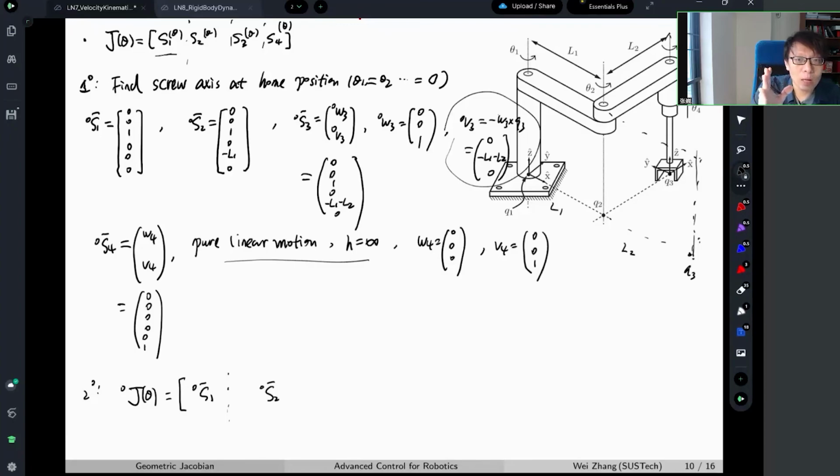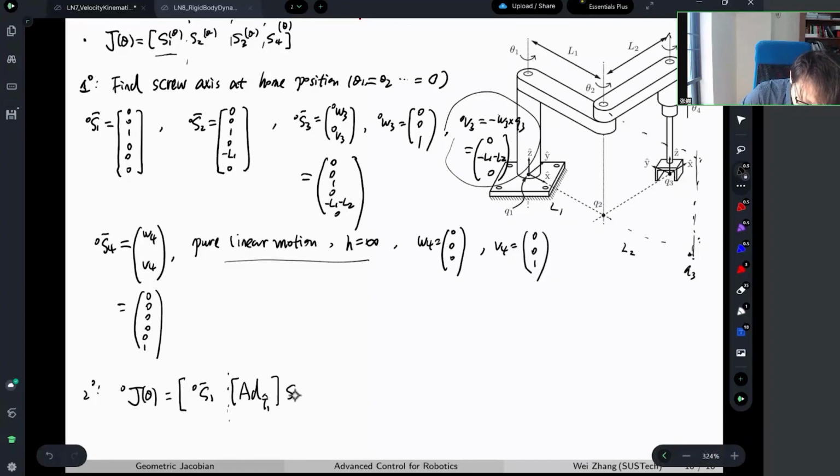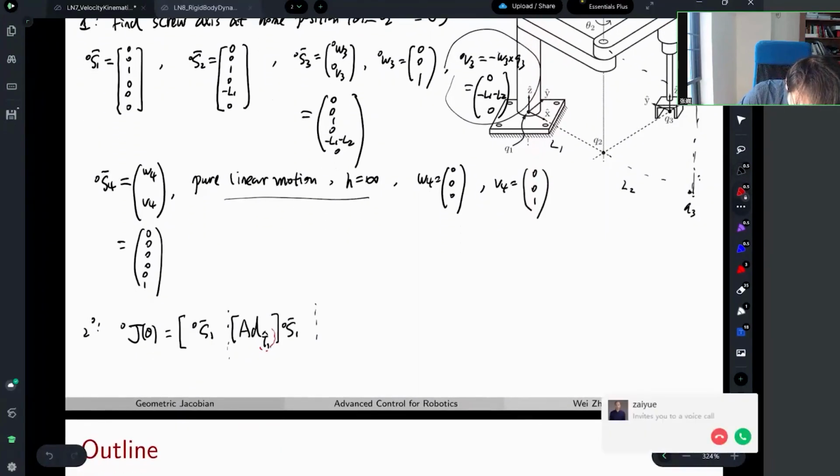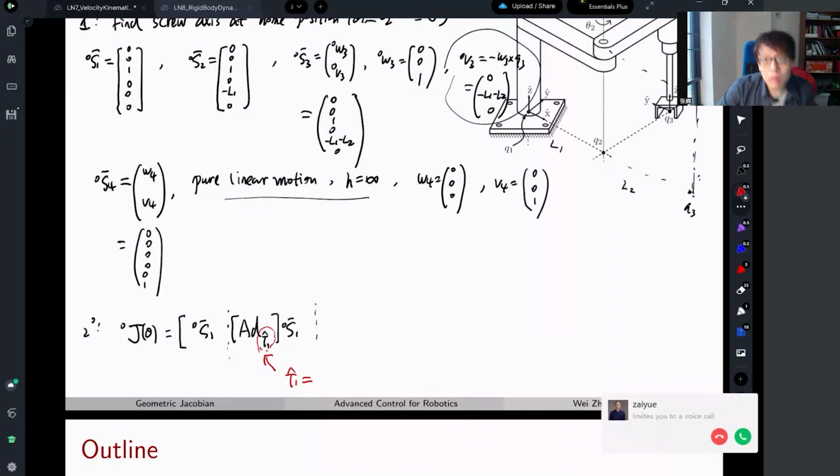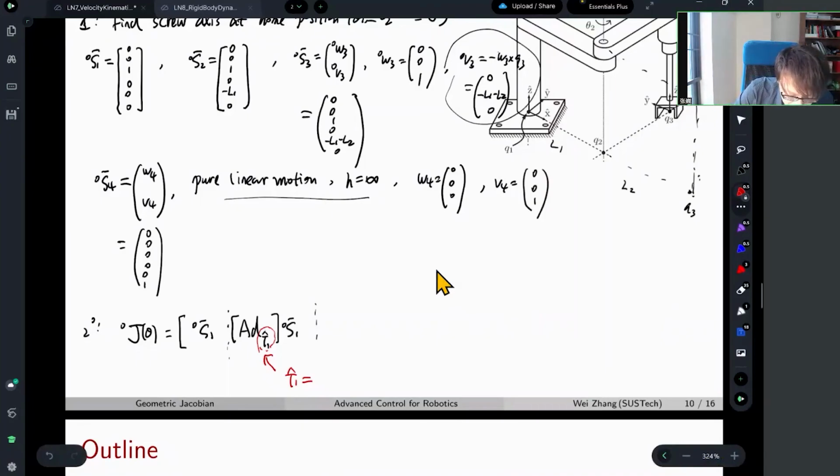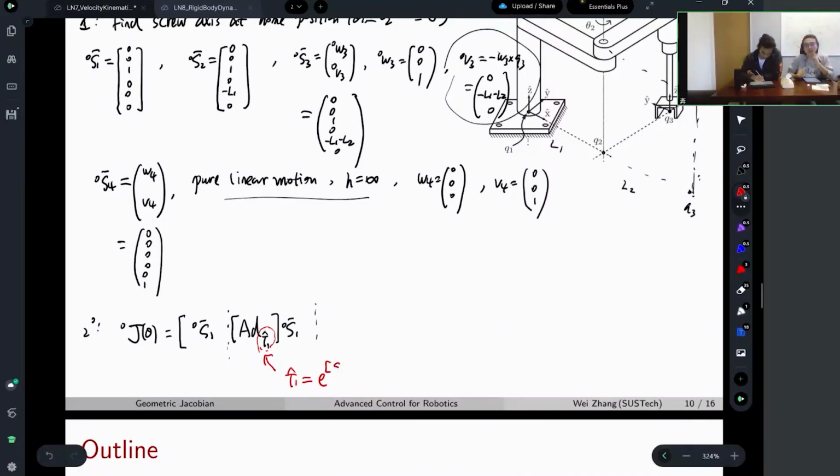But it depends on theta 1, right? Theta 1 changes, that axis moves in the space. And the movement is characterized by this rigid body operator, which for twist will be adjoint T hat 1. Let's call that S1 0 bar. Where I'm going to ask maybe Hongbo, what is this guy? Is Hongbo there? Or maybe Liuben? Yeah, it's E to S1, S1 to 0. Yeah. Okay.